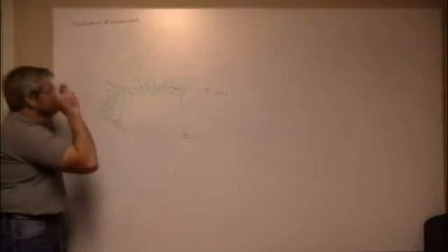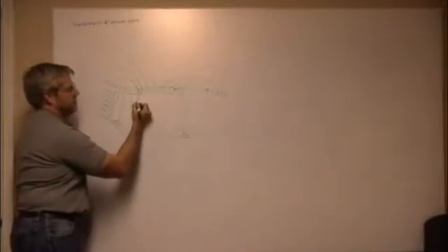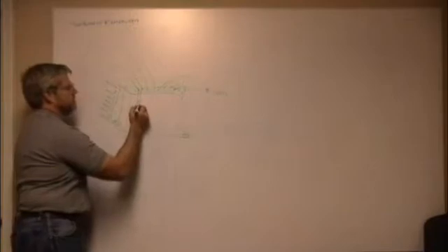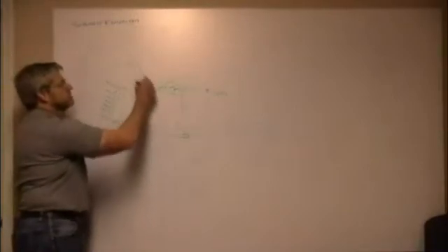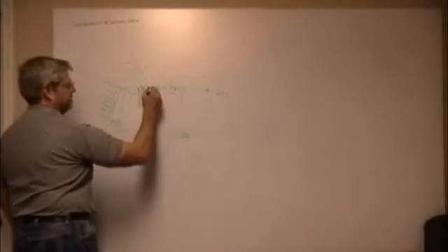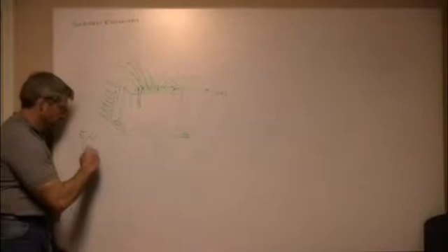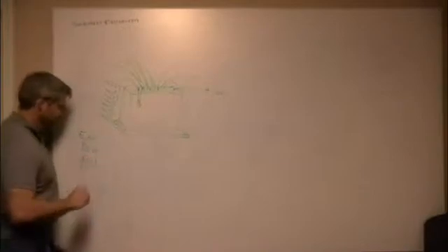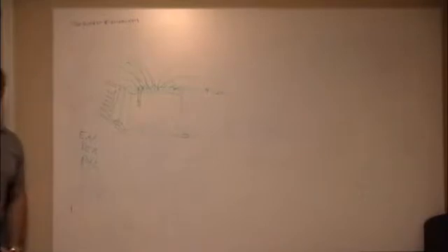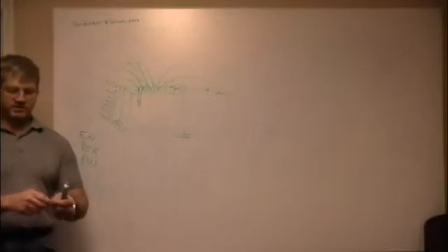This guy uses 3 signals and returns because they're basically internally opto-isolated. So you have to bring in 6 wires to be able to control it. One's a hot, one's a ground. So usually what you do is you just wire all the hots up together and then bring off 3 signal wires. And one is enable, one is direction, and one is pulse. So if it is disabled, you can just turn the motor. The coils are turned off. You play with it all day long. You sit there and spin it by hand.